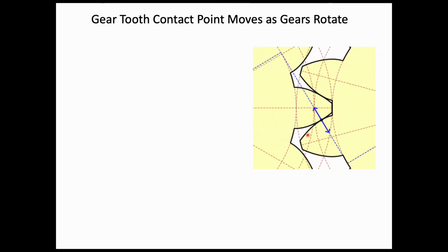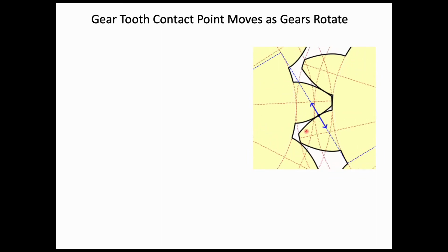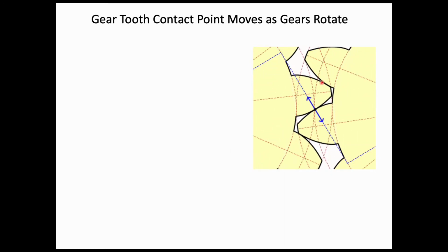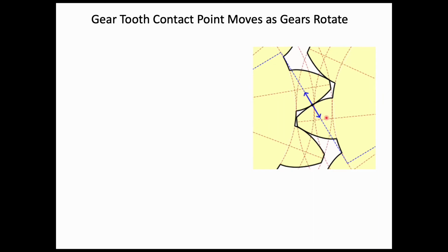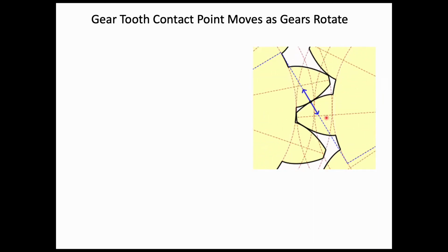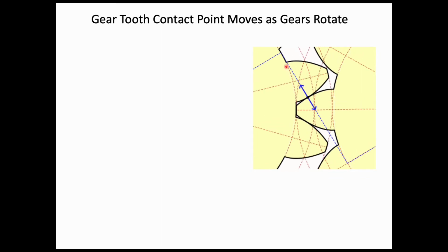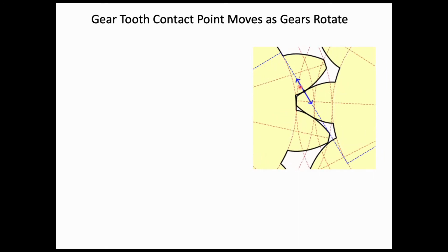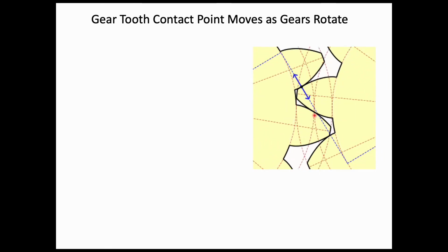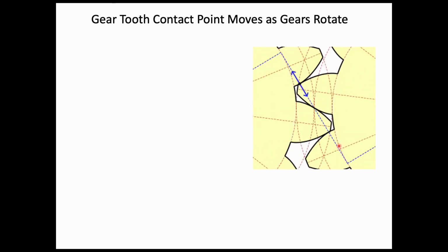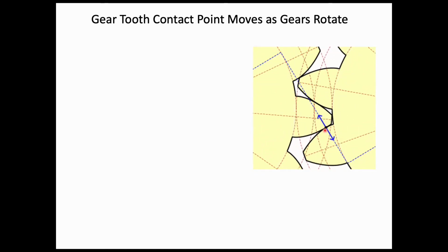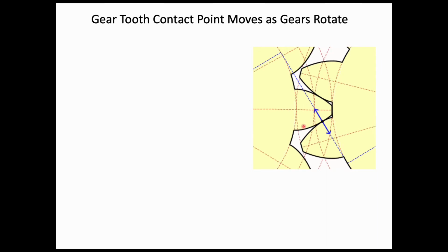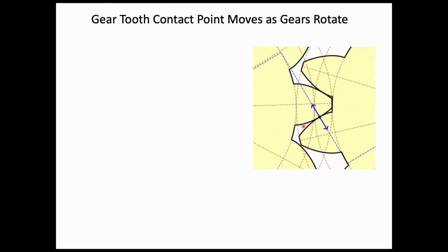Here's a nice animation that helps us to understand many different elements of what we're talking about in this lecture. So as we're looking at these two gears, we're zoomed in at the mesh interface, and here we can see as a pair of gear teeth come into contact, these arrows appear, and these arrows represent the contact force that's perpendicular to the surface at the point of contact. And in this video and other places, I will refer to the point of contact C, and that's different from the pitch point in general.